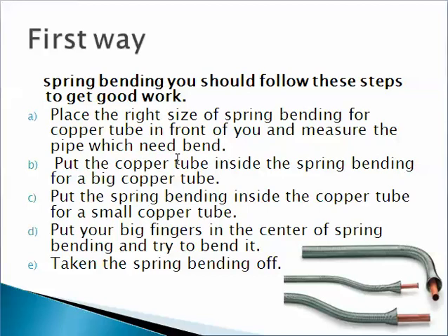B. For a big copper tube, put the copper tube inside the spring bender. C. For a small copper tube, put the spring bender inside the copper tube. D. Put your fingers in the center of the spring bender and try to bend it. Finally, take the spring bender off. Look at this picture to see how it is bent.